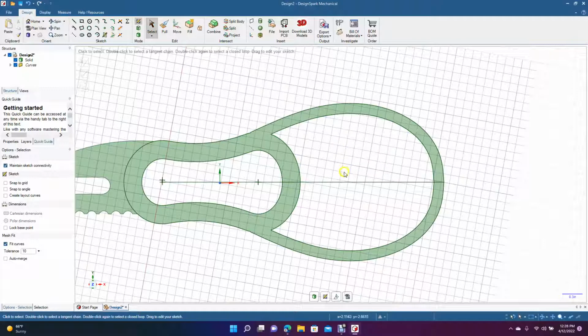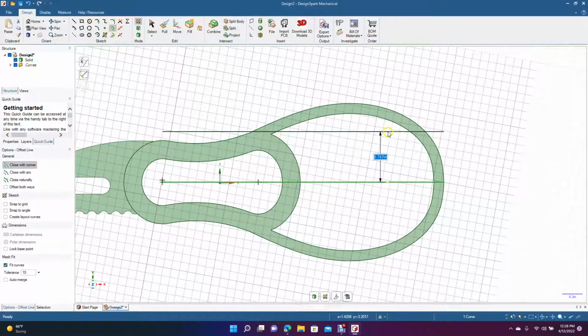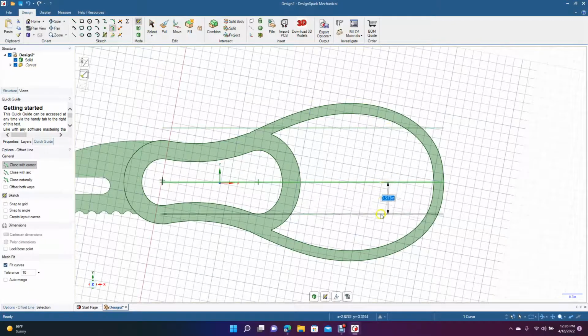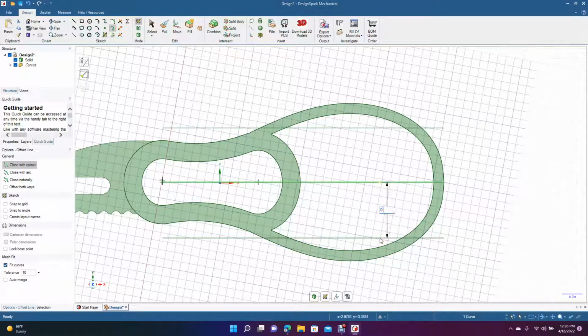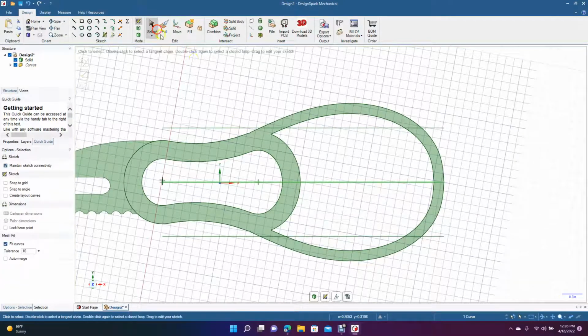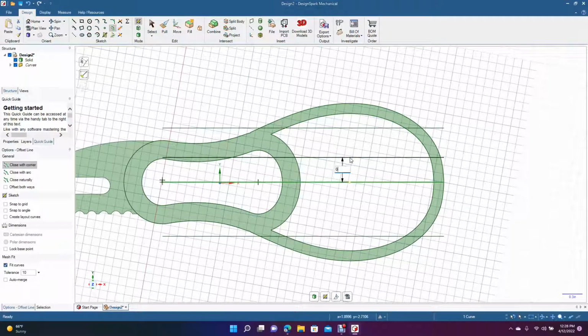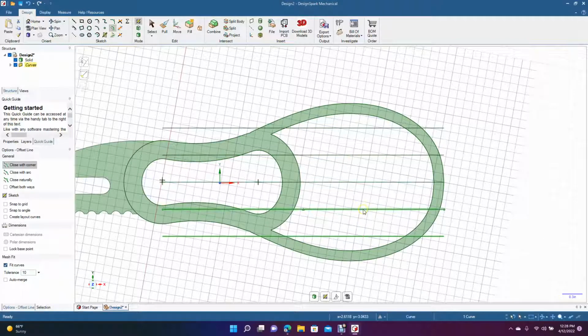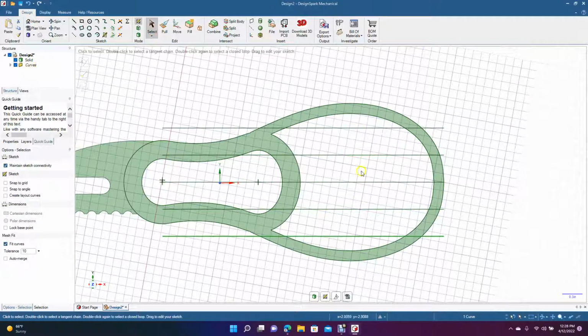Okay, now we're going to go ahead and offset this. So we'll grab our offset. Let's go to 0.8, type that in, enter. Now we'll get the offset again and go to this side, 0.8. Okay. And now we're going to cut the difference in there. So we'll go offset, and then we'll go 0.4, this is half. Click that, come up 0.4. Now we have 1, 2, 3, 4. Okay, there's only 5 scoop cutouts, but I'm okay with that.